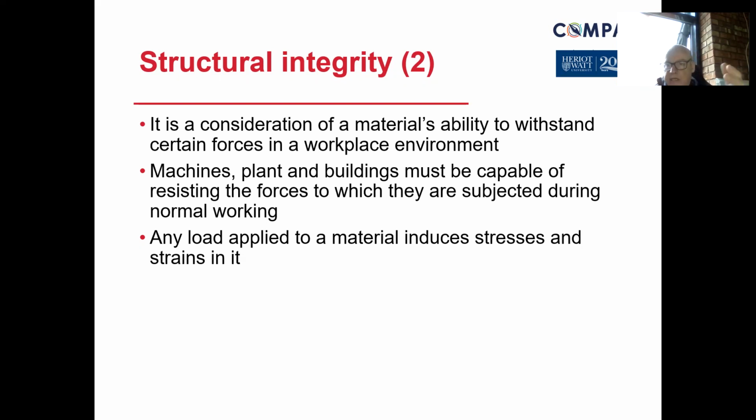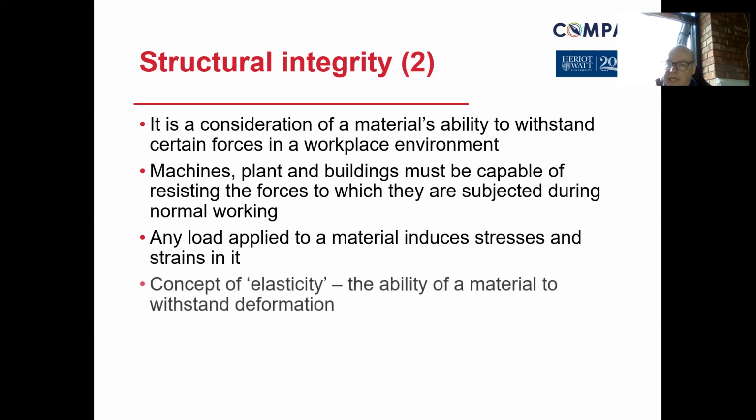Now, usually when you see a change in the physical state of it, it's because it's been induced with various strains and stresses. And it could be that when the chain was being lifted, rather than it being a nice flowing movement, it was under jerking pressures that's gone to the weakest link in that chain and stretched it. So the need for inspections, checks, and thorough examinations are necessary to look at the problems.